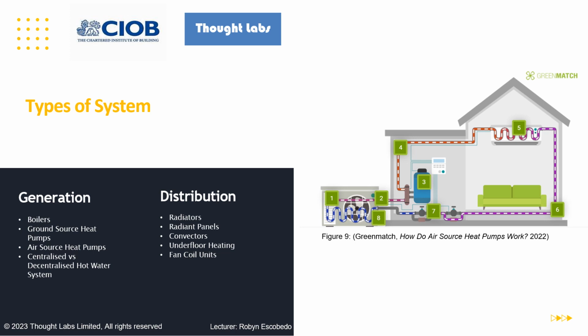However, a real big disadvantage of air source heat pumps is they require a significant electrical supply. This will increase the electrical demand in the building, and if retrofitting, you need to ensure that the supply to the building has capacity and the distribution boards have the necessary ways in order to accommodate the heat pumps. If each heat pump is 63 amps and a medium-sized building has 3 heat pumps for heating and 3 heat pumps for cooling, that is over an additional 300 amps, which is a significant amount.